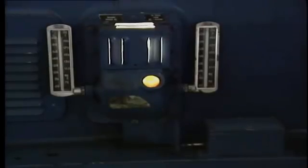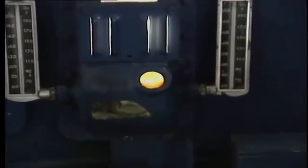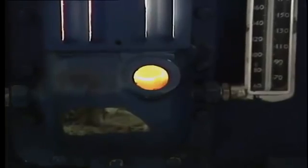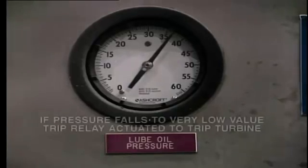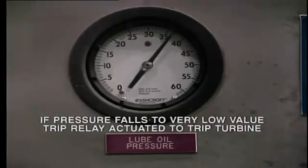Another condition which will cause the turbine stop valve to trip is loss of lube oil pressure. If lube oil is not available to provide lubrication to an operating machine, the bearings will rapidly overheat and fail, with possible disastrous consequences for other components of the turbine and generator. Lube oil is monitored continuously, and if pressure falls to 0 or a very low value, a trip relay will be actuated to trip the turbine.